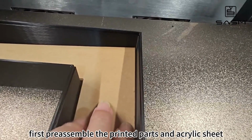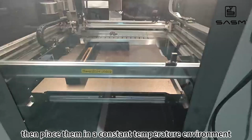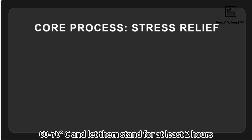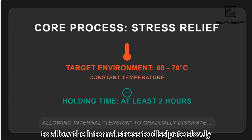Specific steps: first, pre-assemble the printed parts and acrylic sheet, then place them in a constant temperature environment of 60-70°C and let them stand for at least 2 hours to allow the internal stress to dissipate slowly.